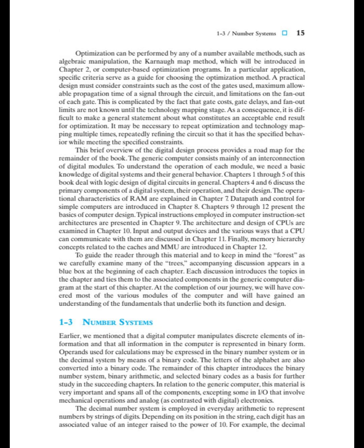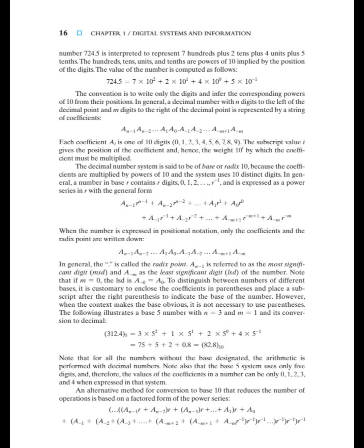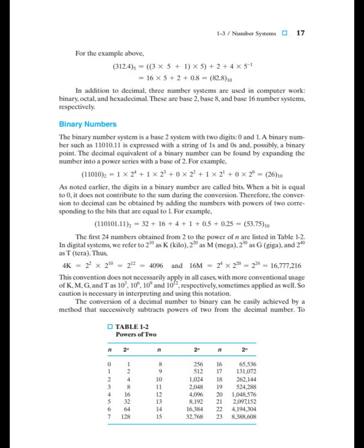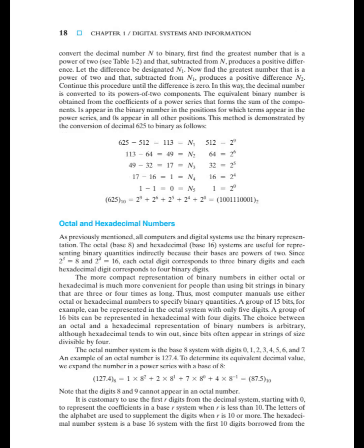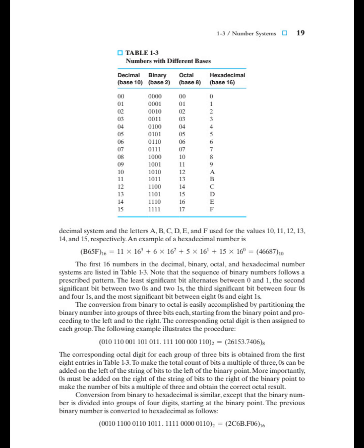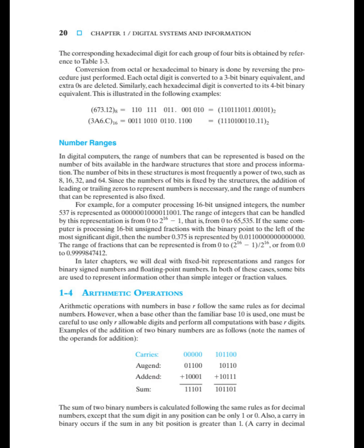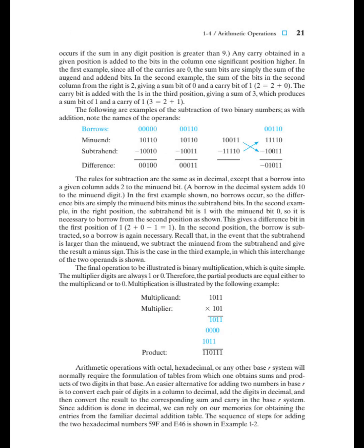What are those used for? They have a special property where only 1 bit changes between consecutive values. This makes them great for things like optical shaft encoders that measure rotation. Why is that? In a normal binary code, multiple bits can change at once. If the sensor is right at the transition point, you can get weird readings. But with the gray code, only 1 bit flips, so it's much smoother, no ambiguity. So they're used for specific applications. They are. They also have advantages in low-power circuits.